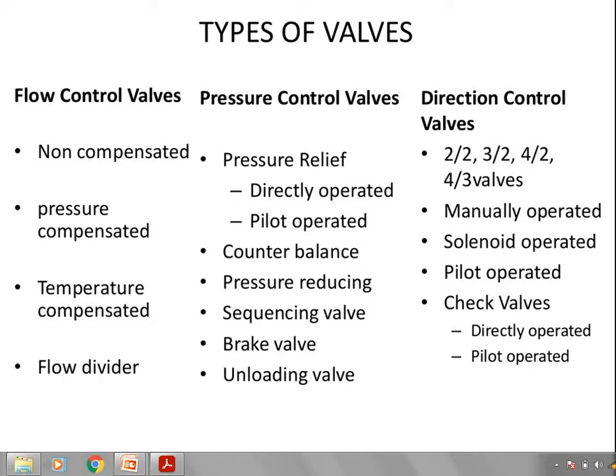Okay. So already you have gone through similar kinds of control systems in the hydraulic part. As you know, you can go with the hydraulic system or pneumatic system. There are basically three types of control valves, that is DCV, PCV and FCV, meaning direction control valve, pressure control valve and flow control valve. These are three very important control systems in a pneumatic system as well as in the hydraulic system.